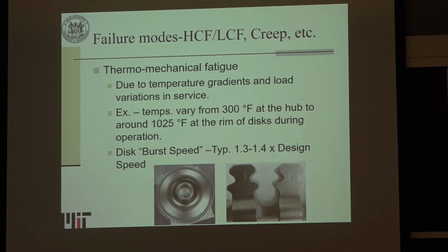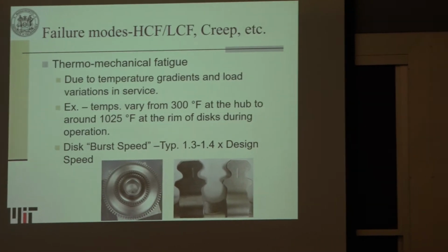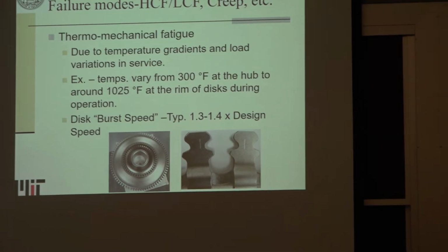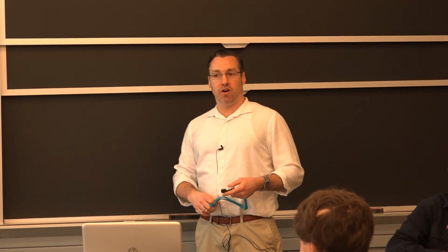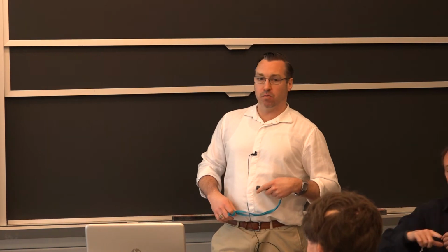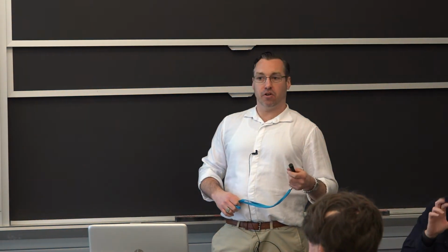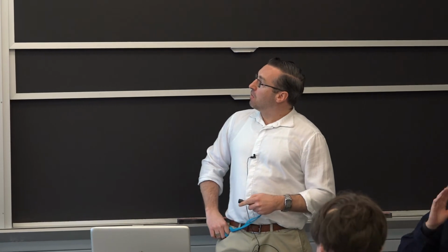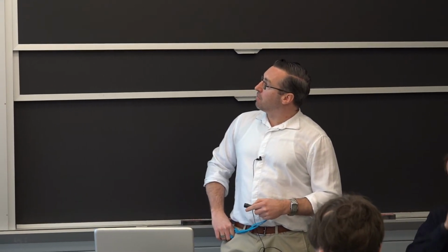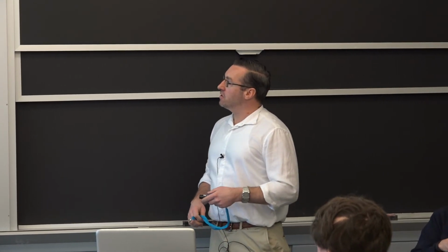So you figure these planes operate basically nonstop. It goes from one location to the next. It starts acquiring cycles. So both high cycle fatigue and low cycle fatigue are very important, as well as creep, because we're dealing with high temperature mechanical degradation. So you have thermomechanical fatigue due to temperature gradients and load variations.